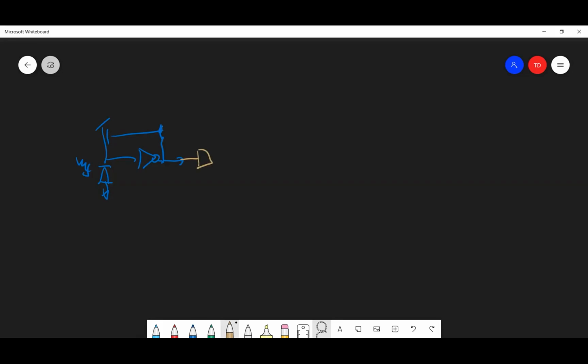you might need a buffer on it, like a unity gain buffer to isolate it, just like a source follower. And then what if you take a capacitor like this and another little one like this and just wrap an amplifier around it, an inverting amplifier. I draw it abstractly like a digital inverter, but it's just like this inverter on the left here. It's just like a high gain inverting amplifier. And then we'll put a switch across this. Okay, so what does that circuit do? Let's say this is C1 and this is C2.